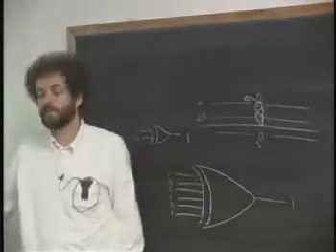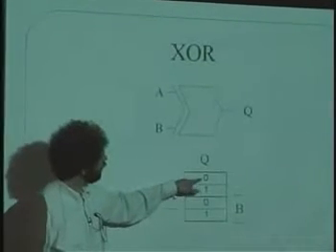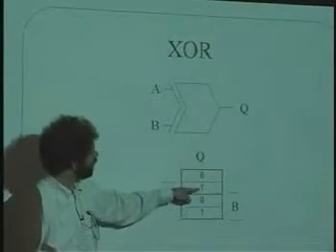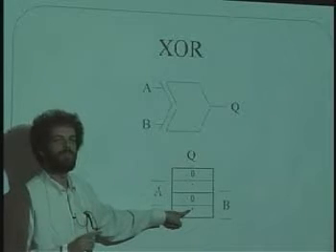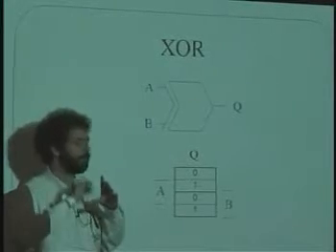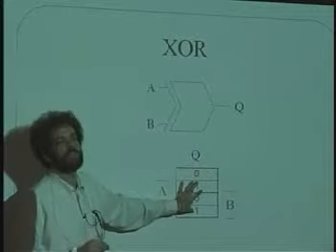And that's why when you look at a K-map of something that has XOR in it, you always see this checkerboard or chessboard type thing where it goes 0, 1, 0, 1. Why? Because in the K-map, as you move from one square to the next, exactly one input is changing. And you know that the XOR of something where one input changes switches from 0 to 1. So it has no choice but to act like this.